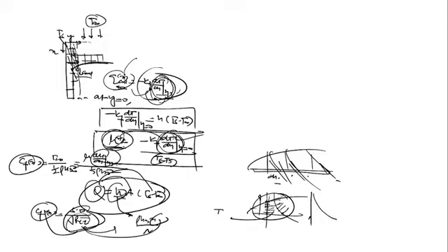Is this clear, beta? Because the whole problem is only with the fluid motion; the problem of conduction is not in solids, it is only in the fluid. We can't use the convective heat transfer in the whole fluid, because convection is only there when the fluid is in motion, and that is only away from the wall. Clear?